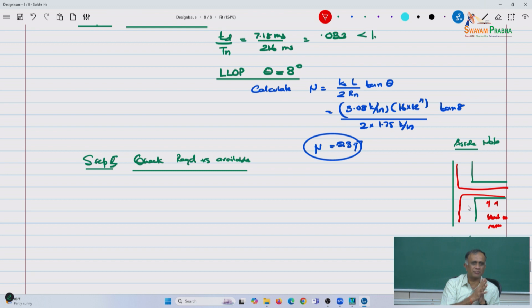Other things that are done, for example, you could design, if you've heard of strut and tie methods, right? In connections, you will calculate your dynamic reactions. Some of you in concrete would have heard of strut and tie. Strut and tie methods are very frequently used in the design of connections. It's a good method to use in blast design. And then how would you reinforce in a strut and tie method? Based on the strut and tie diagram that you are drawing. So your reinforcements could go in the direction of the ties, which are non-standardized apart from your regular reinforcement.